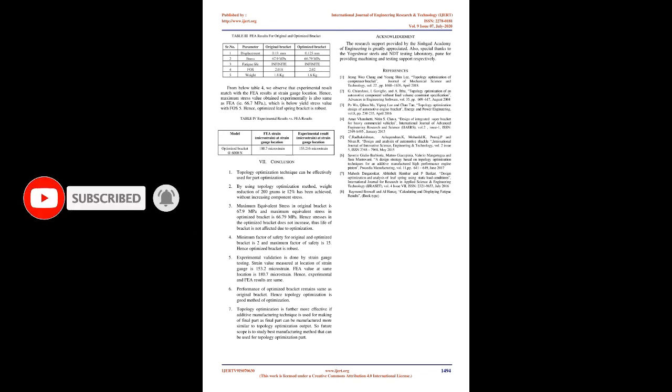7. Conclusion. 1. Topology optimization technique can be effectively used for part optimization. 2. By using the topology optimization method, a weight reduction of 200 grams, i.e. 12%, has been achieved without increasing component stress. 3. Maximum equivalent stress in the original bracket is 67.9 MPa and maximum equivalent stress in the optimized bracket is 66.79 MPa. Hence stresses in the optimized bracket do not increase, thus the life of the bracket is not affected due to optimization.